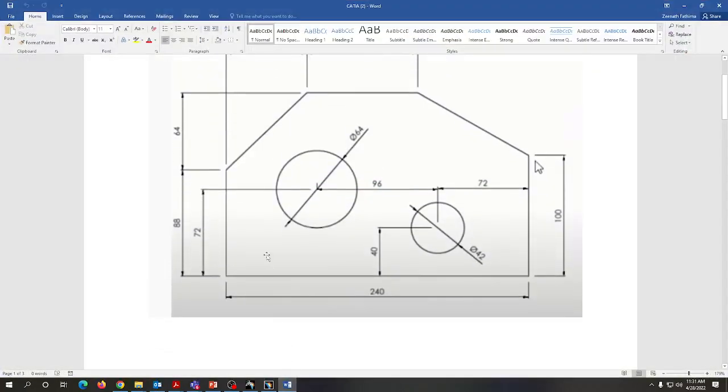another line, like we need to create this circle here. These 2 circles I have to create inside my object. So here I have got one closed object, or closed line feature. Now I am going to create the circle over here. First I will randomly draw the circle, then I will give the center line. To locate the center of the circle, I will give the horizontal distance and the vertical distance. So I am going to locate the circle now.